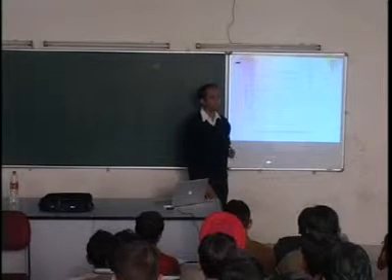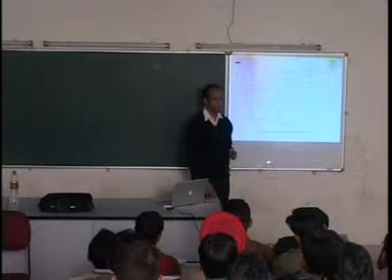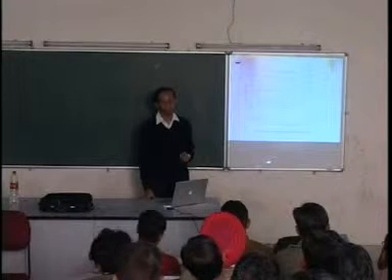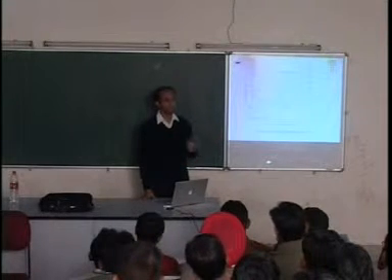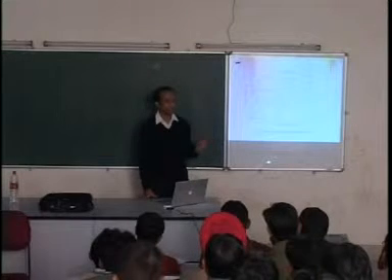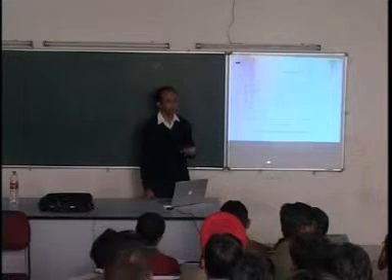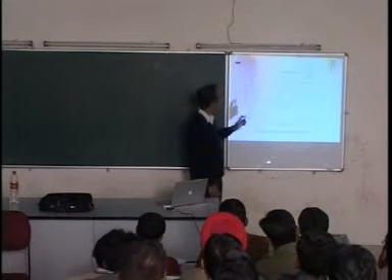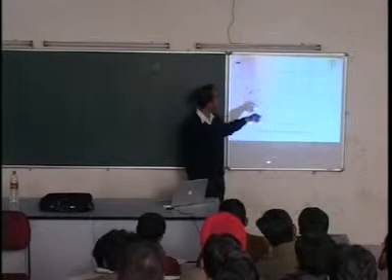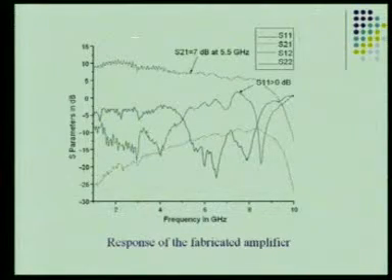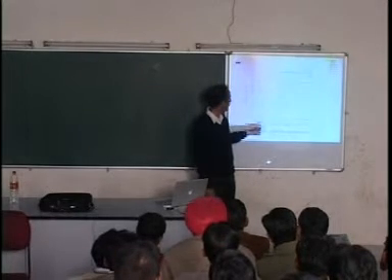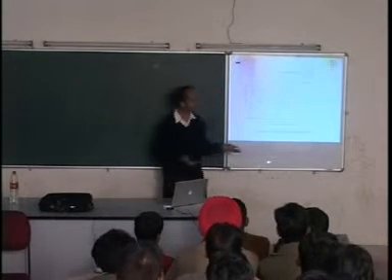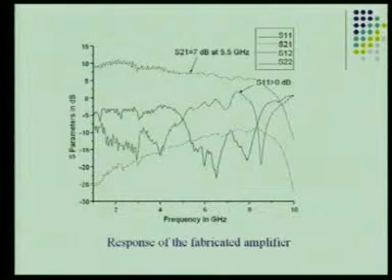Do you know what S parameters are? S parameters is another topic which unfortunately is loaded with all kinds of gray areas. A lot of people have a lot of different ways of explaining them, so I will not go into those problem zones. In this case it is very simple. S21 is the gain of the amplifier. S12, this small one, is the reverse gain. Obviously it is supposed to be very small. S11 is the reflection coefficient.